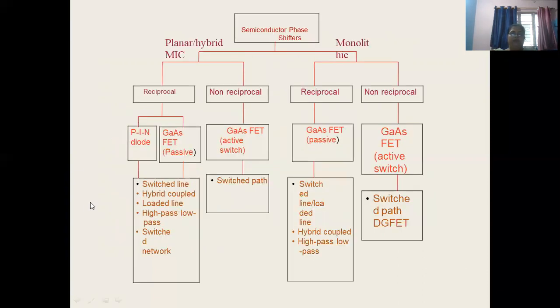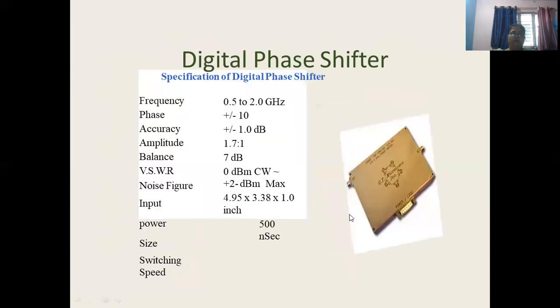This is the broad classification of the semiconductor phase shifter. These are divided into planar or hybrid, monolithic. Then these are divided into reciprocal, non-reciprocal. Here it is also reciprocal, non-reciprocal. This is PIN, gate FET, GaAs (gallium arsenide) FET, passive and active switch. PIN and the passive phase shifters are used as switched line, hybrid coupler, loaded line in high pass, low pass switched networks. So this is the general classification of the semiconductor phase shifter.